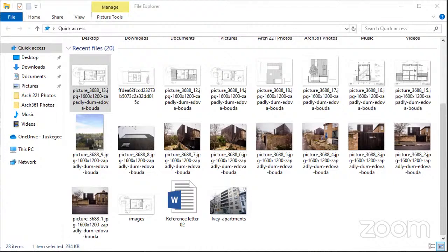But we can say a typical diameter for a toilet or something standard is what you would usually do if there are no dimensions on your building. If there are no dimensions on your existing building, you would find a standard size object in the drawing and scale it using that object. Does everybody kind of understand what I mean by that? Or nah?